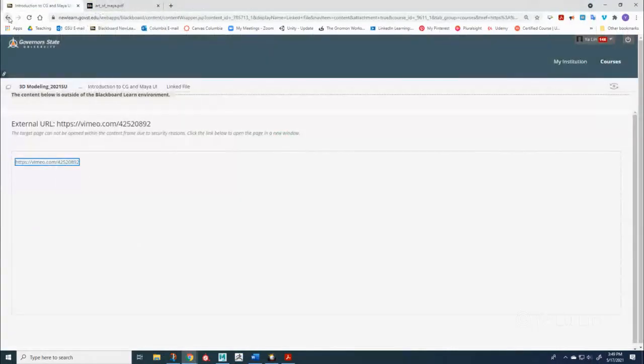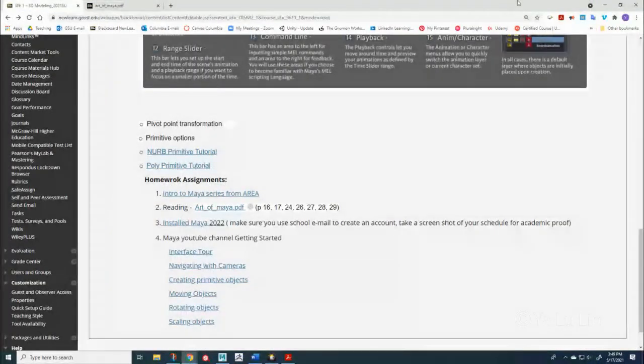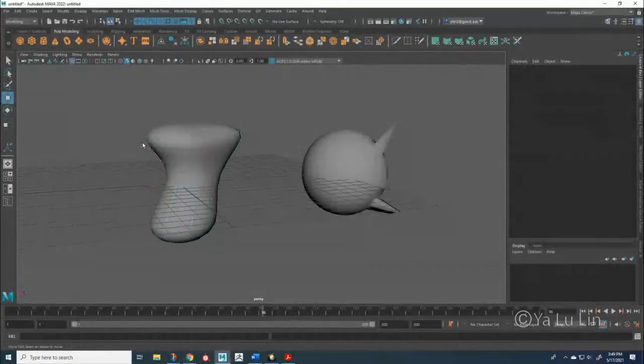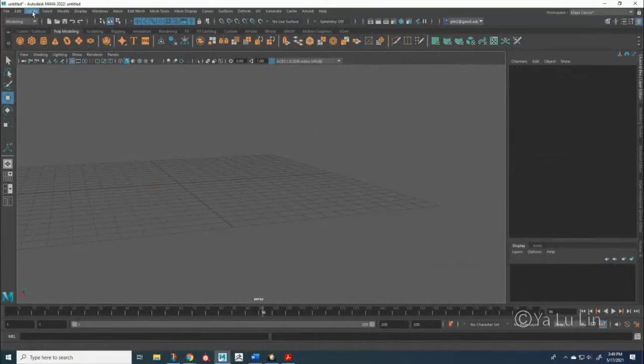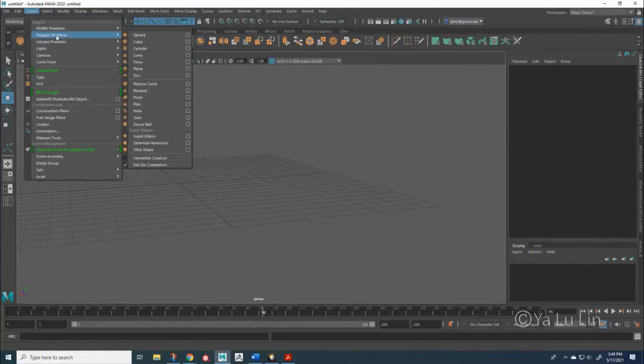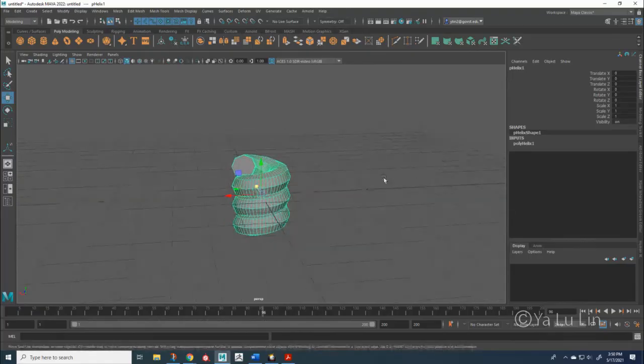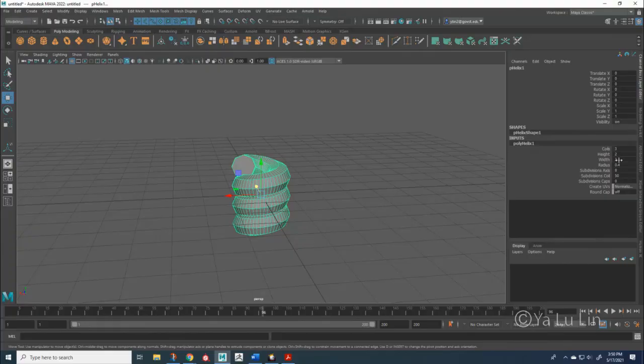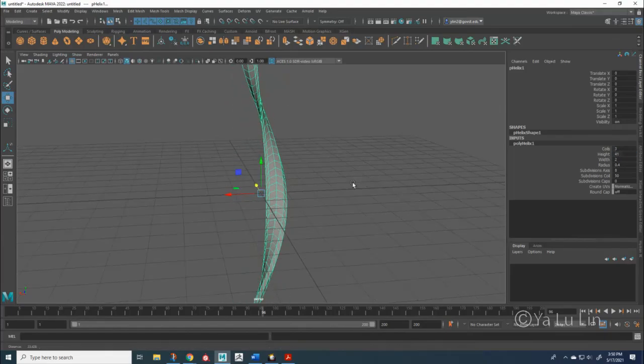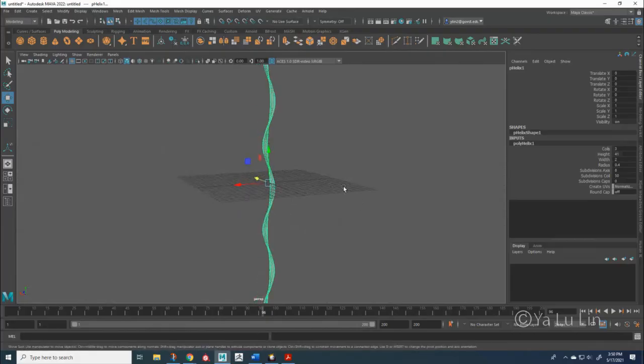So I'm going to squeeze one more primitive in here because I do think they are fun. And let's go ahead and do helix. Okay, so we'll do helix here. Create polygon primitive helix. There it is. So with the helix, I can go ahead and enable my option in my input. So input poly helix 1. Let's highlight the height because I want it to be tall enough. Okay, so that's pretty tall. Then you can always press A to frame all of it.